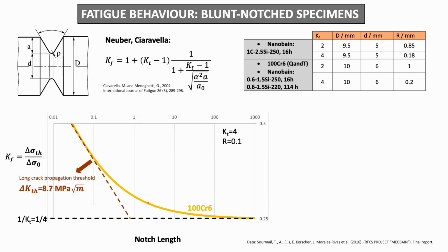propagation is not enabled. And it means that when we have introduced a notch, there is a volume effect, there is a size effect, and therefore the volume of material that is subjected to critical loading is important.